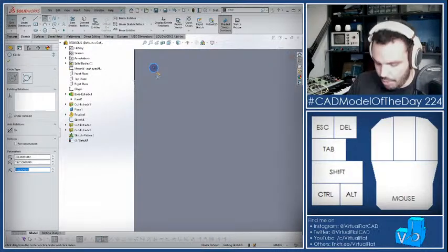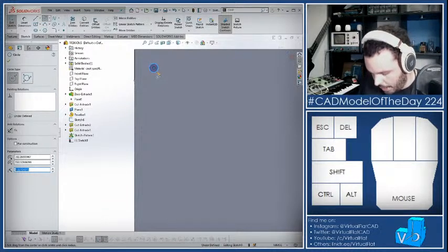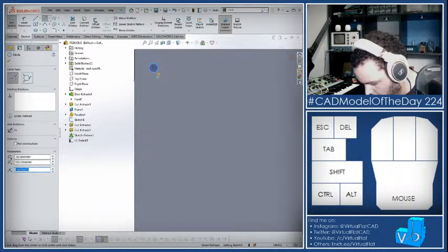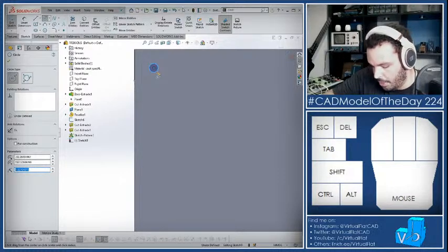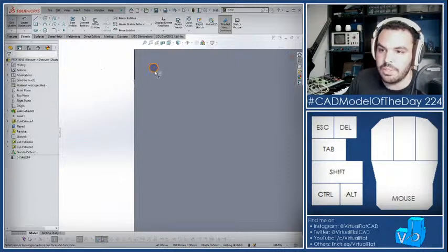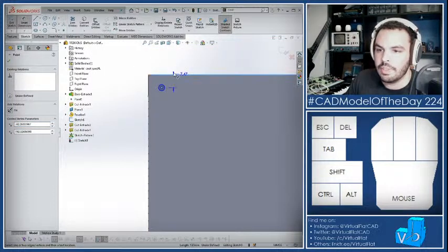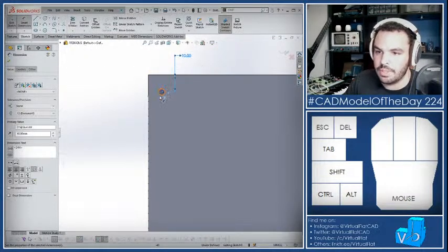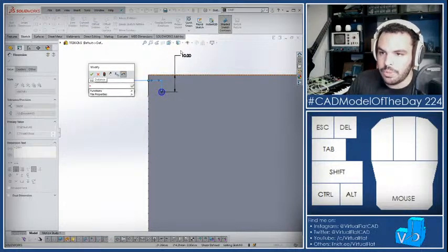So I'm just going to drop a circle right there. This thing is designed in metric, so these are coming out to be nice whole numbers. I'm measuring those little divots, and they are 10 millimeters from each side. Isn't that awesome? I love it. If I grab that, that says 10, and I can say equals 10.